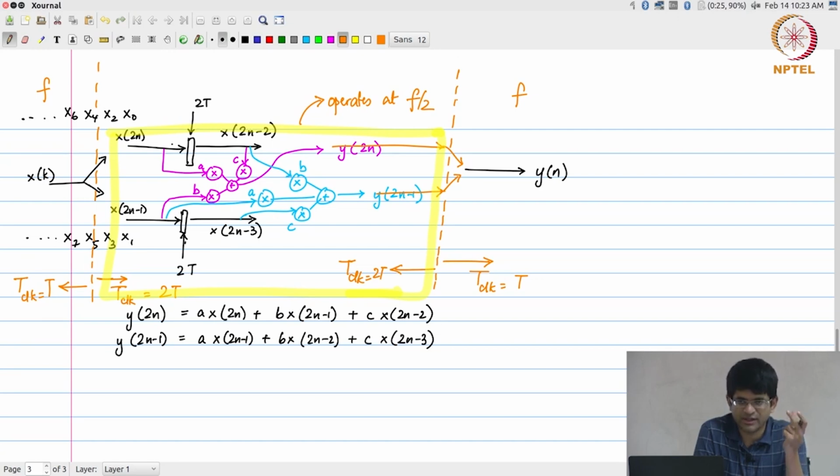this is one part where you need some familiarity with digital IC design. What is the connection between the operating voltage and the propagation delay through a circuit? In general, if I increase the operating voltage, keeping the technology otherwise the same, would I expect to see an increase or decrease in propagation delay? I should see a decrease, right. In other words, the circuit can switch faster, right.